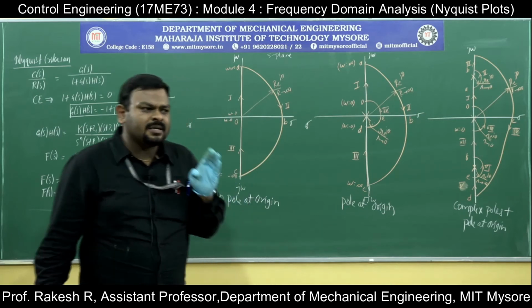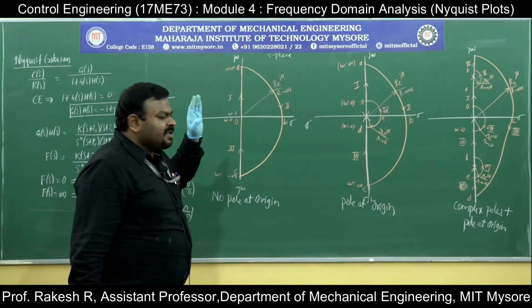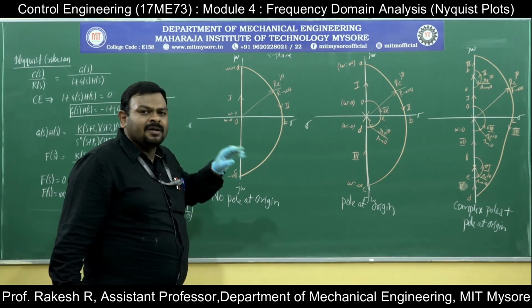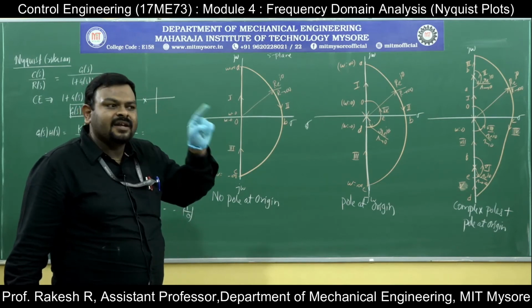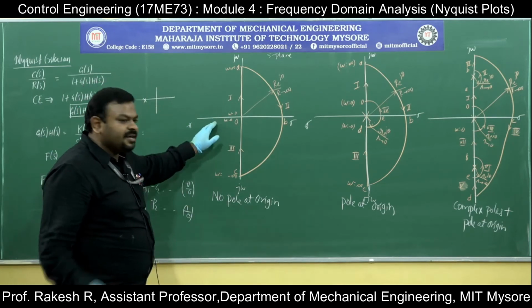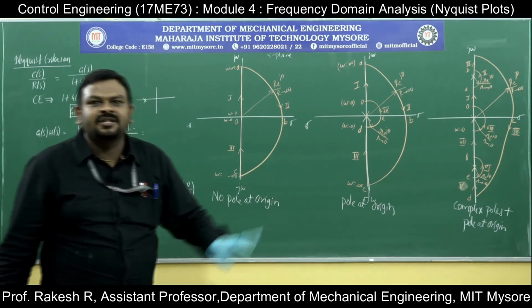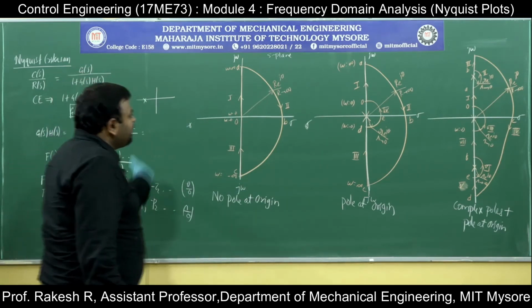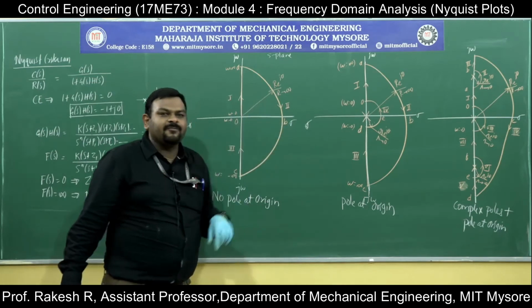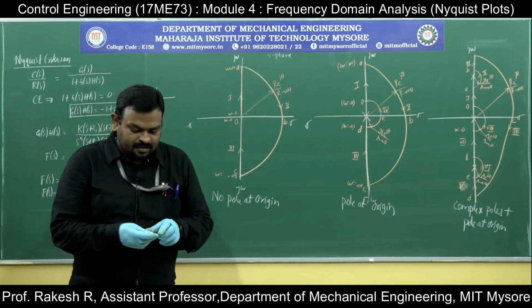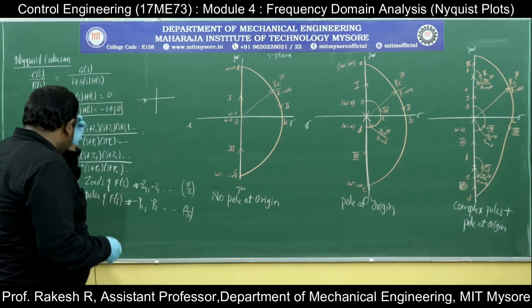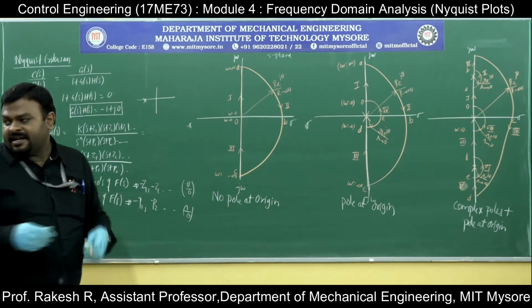What he has done is, he has searched the entire path in which the system will be unstable. Here, on the left hand side, no searching, because if there are any poles or zeros there, the system will be stable. But if it is on the right hand side, the system will be unstable. With this, Nyquist has given the Nyquist criterion.